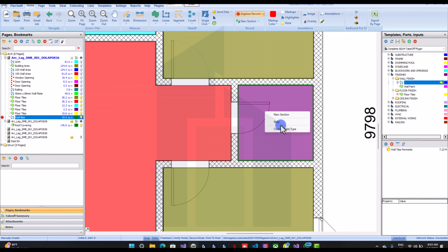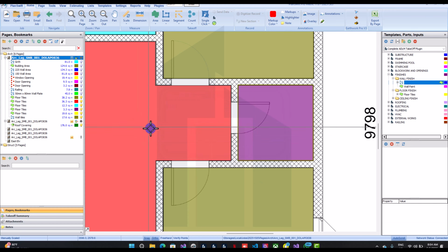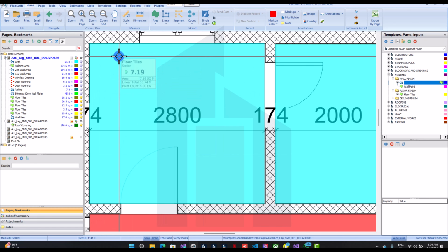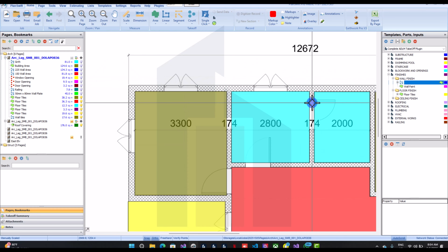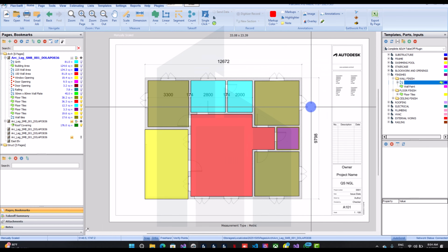So once you've done that, for the door, since it's just a single door, just double click on this door area. That will be 0.9 times 2.1, so just 1. Okay, so we have that deducted. For your kitchen backsplash, probably we have a black kitchen wall tiles. So just leave this like this. Let's just leave the kitchen as it is. I think that should be all for this.